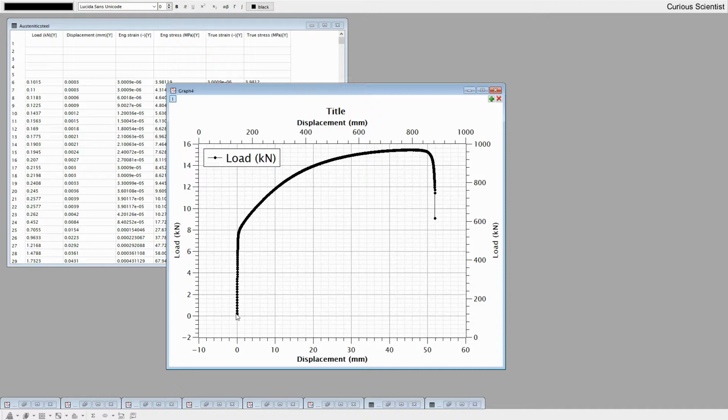And you can see that from the start to the fracture, the material had more than 5 centimeters of elongation, and then we reached like 15 kilonewton load as the highest load. So yeah, this is the most basic, but we cannot really use this material, so this curve, it's not so informative for us.